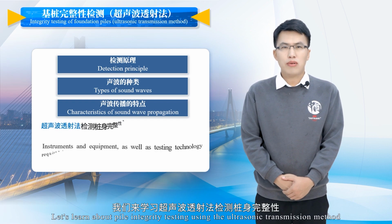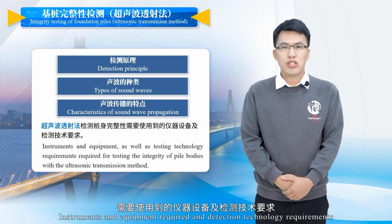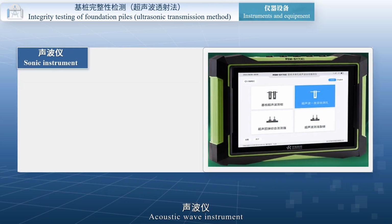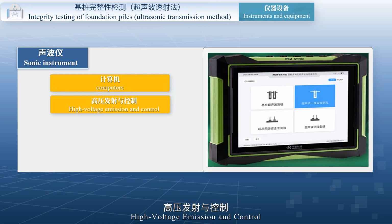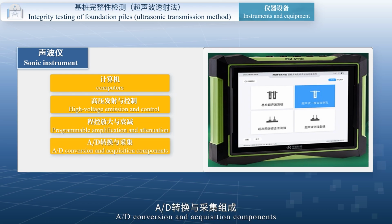Next, let's learn about pile integrity testing using the ultrasonic transmission method: the instruments and equipment required and the detection technology requirements. The acoustic wave instrument is controlled by computer and includes high voltage emission and control, programmable amplification and attenuation, and A/D conversion and acquisition components.